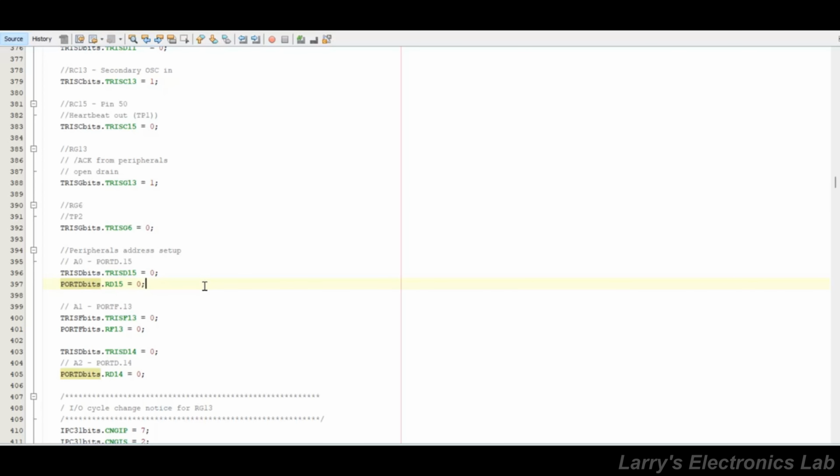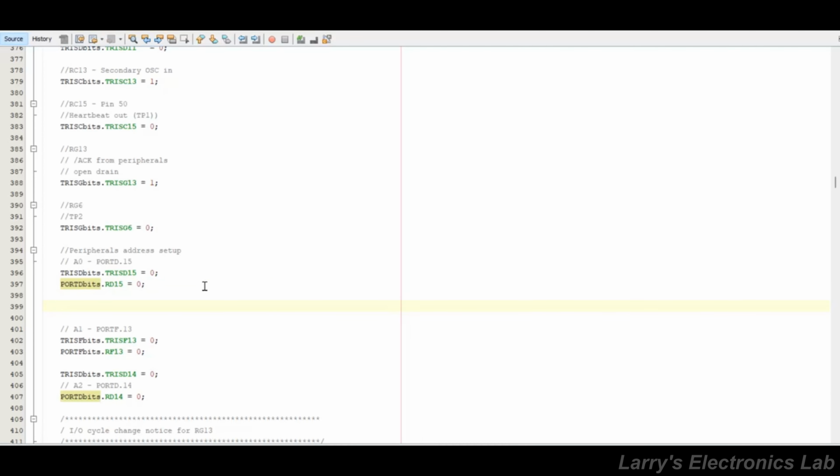Okay, so in the Microchip environment, when you type PORTG or whatever port you're talking about, it gets highlighted as a register, equals 0x45. So that would put 45 in port G like we were talking about. But if you want to do the bits, then you just add the bits part, and it doesn't highlight as a register, but when you hit the dot, then you get the selection for the structure.